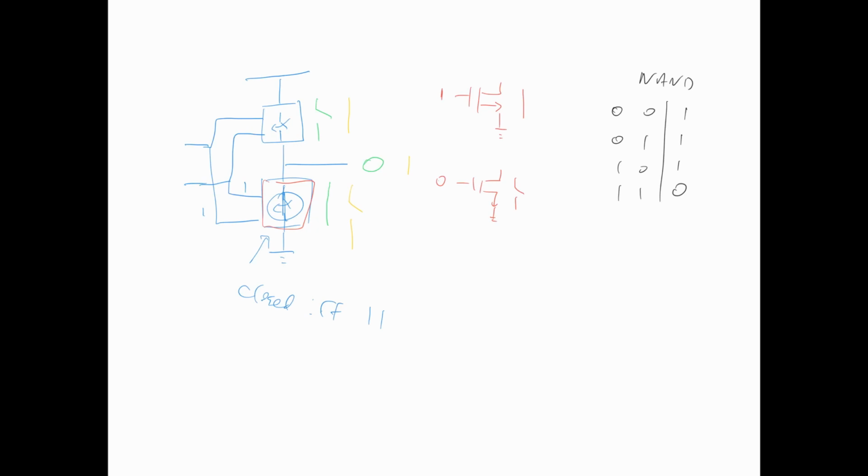Remember, we said it was not possible to design an AND gate directly. We'd have to have a NAND gate followed by an inverter. Well, that's why things work out. Because this NAND gate is a so-called inverting gate, we require this switch here to be closed if both inputs are 1, and an n-channel FET does have the switch closed if the input is a 1, so therefore it is possible to make this design. If we were trying to do an AND gate from scratch, we'd get into trouble here not being able to complete this, and that's why to do an AND gate we have a NAND gate followed by an inverter.